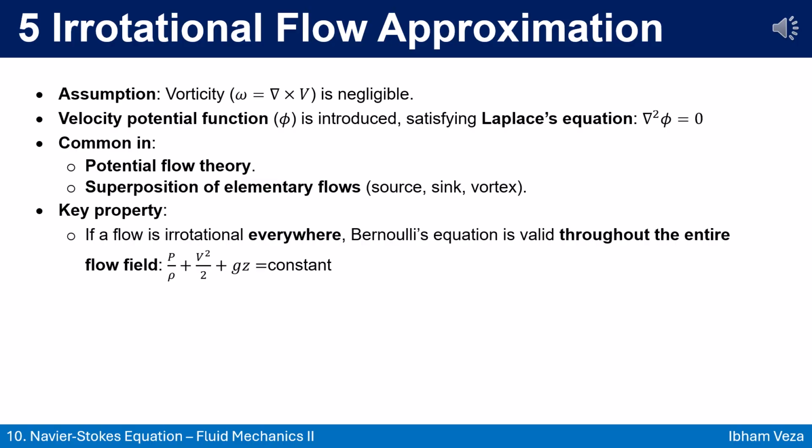This shift turns the problem into one of potential flow theory. Instead of solving complex nonlinear Navier-Stokes equations, we solve Laplace's equation, which is linear and much easier to handle. It allows us to build flows by superimposing simple solutions like sources, sinks, and vortices into more complex patterns.